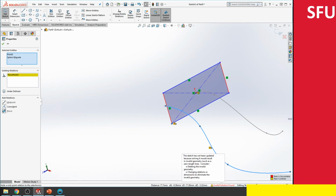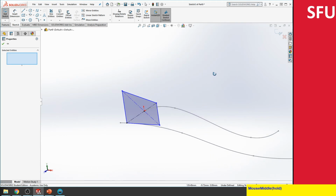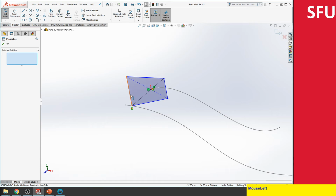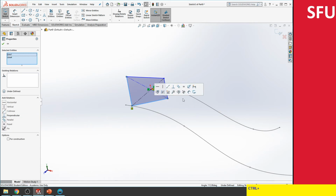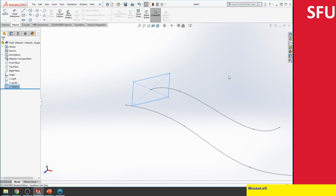It just doesn't want to do a constraint. The reason is that there is this horizontal constraint over here. So let's just delete these constraints. And now we're able to do the pierce constraint. Then maybe we just want to make sure it doesn't get too haywire, so we want to minimize the twist. Maybe I can make these two perpendicular, and maybe this and this perpendicular as well, and this perpendicular. This will ensure I'm keeping a more or less rectangular shape.